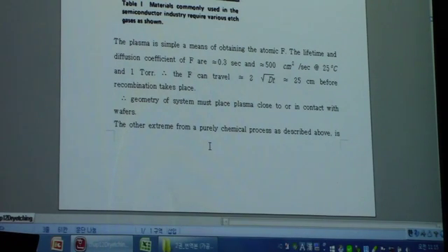So after 0.3 seconds, the fragmentized CF3 gas and F atoms are going to recombine to form a CF4. Once it is formed the CF4, it is not going to work as an etchant at all. So everything has to be done within 0.3 seconds, in other words.